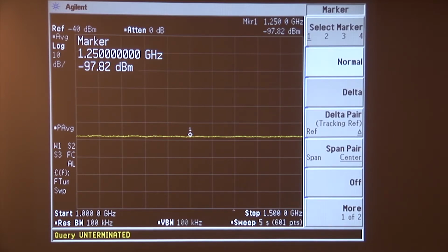So if we use the equation that we derived on the whiteboard, we'll go ahead and do this real quick. Capital Y is 6 dB. We'll divide that by 10. That's 0.6. We take 10 to that power. That's 3.98. We subtract 1. That's 2.98. We take log of that number. That comes out to be 0.4744. 10 times is 4.7, and here's the key part: this noise diode has calibration factors stamped on the side. It's supposed to be a 25 dB excess noise ratio diode, so we subtract 4.7 from 25, and we get 20, I did that wrong, 25 minus 4.7 gets us 20.3.